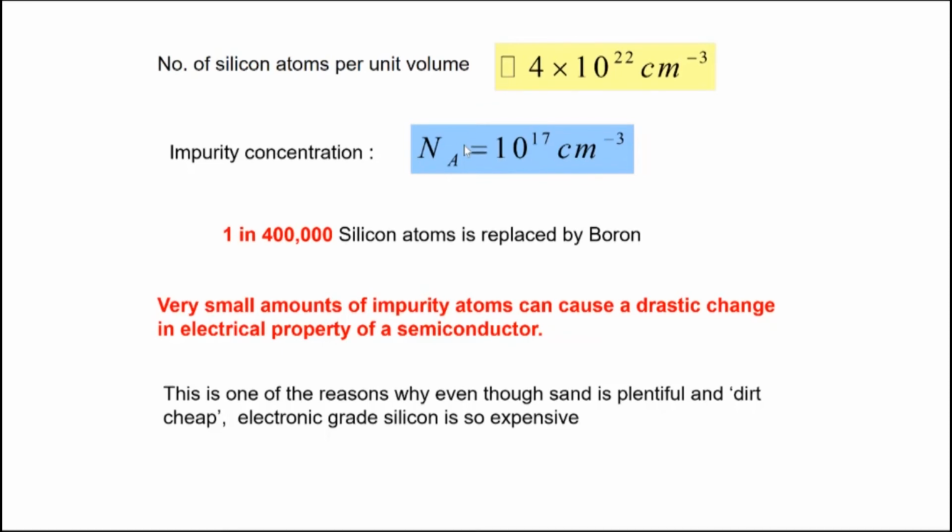And it's one of the reasons why semiconductors took some time to become common. When people started working with semiconductors, the semiconductors that they had were not very pure and had a lot of impurities to begin with. Different scientists and different researchers would get different conductivities, and it was very hard to work with silicon. Real progress in silicon started only when people could purify silicon to a very high degree. Once you get very, very pure silicon, then you can add impurities in controlled amounts and study the effect of that impurity. You can create devices. That's why silicon in extremely pure form is very, very important, and it's one of the purest materials on earth.